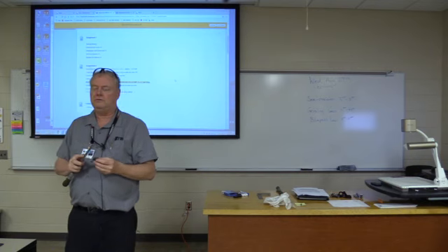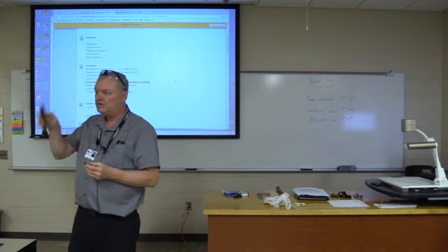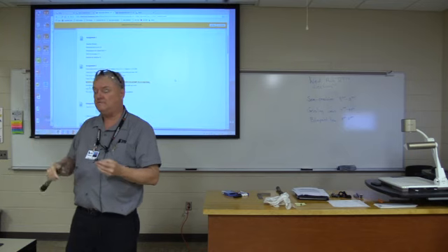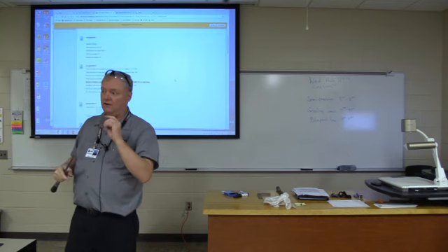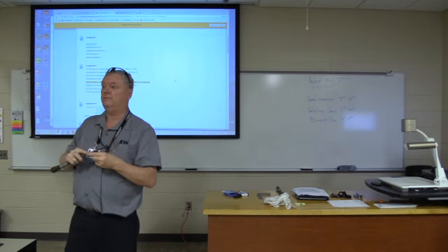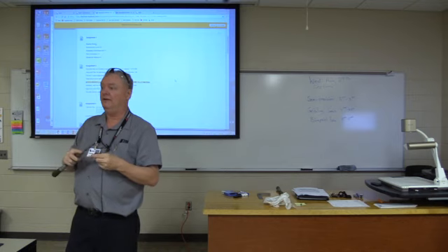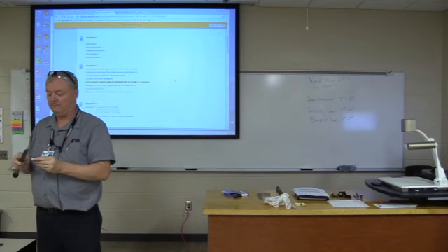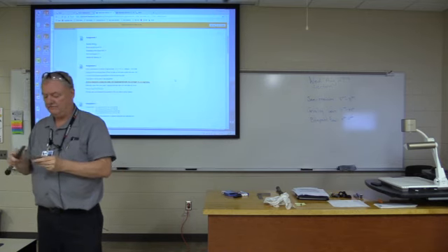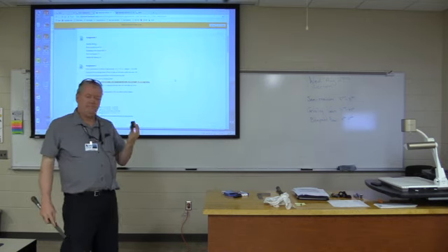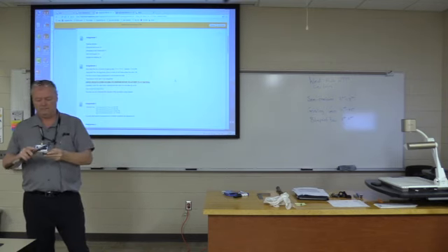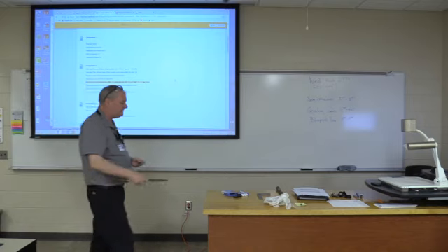Yesterday, some of you used the 1 inch diameter aluminum, and you measured it, and you saw it was a little bit oversized. Rough material is always a little oversized, but you can pretty much count on it not being under. If it is undersized, you send it back to where you bought it from and tell them you got a bad piece, because they shouldn't be under. Okay, so this all comes from the bandsaw. Edges get cleaned up.